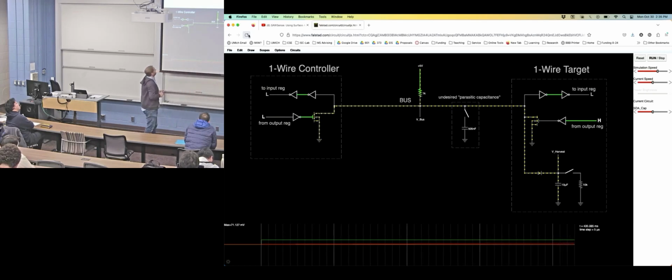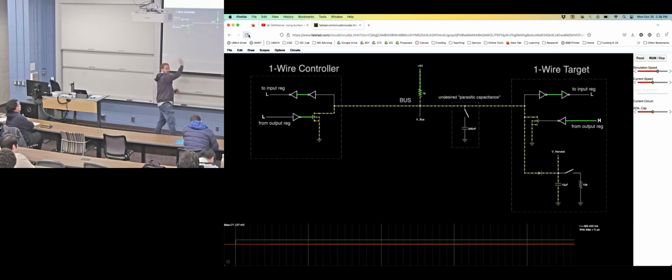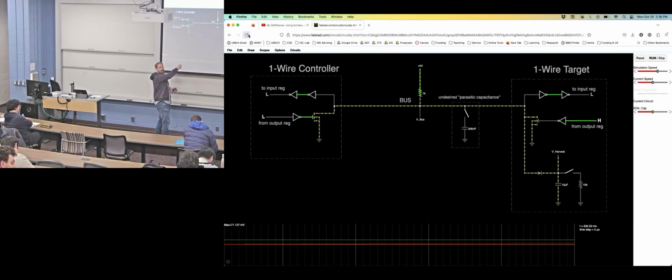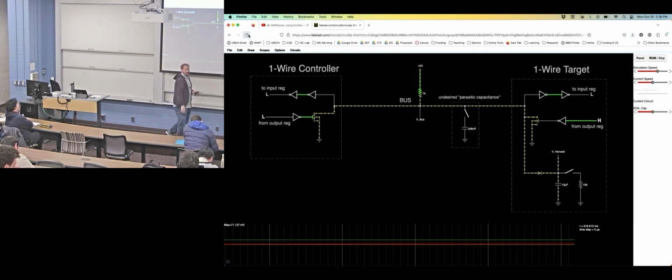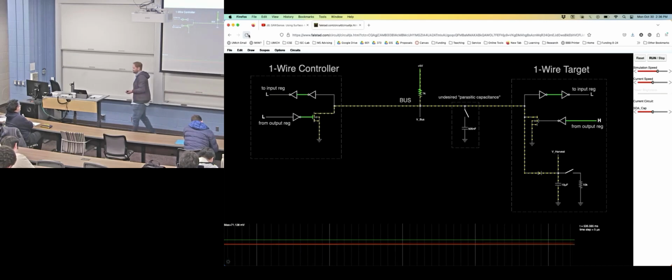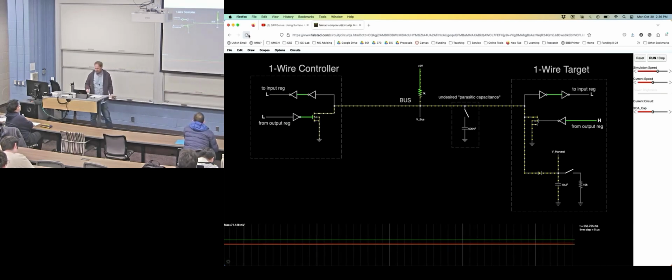What else do you need to know? You're going to have to do asynchronous clock recovery, not shown on this diagram, but you'd have to use the UART method of oversampling to figure out when to sample clock and data. So that's the extra tricky part. Any questions about that before I talk about the power part?